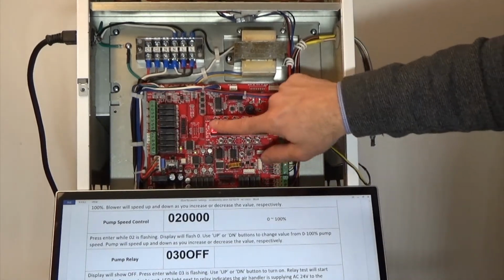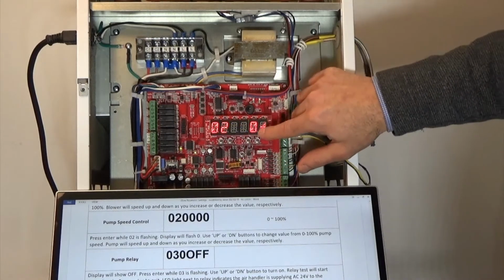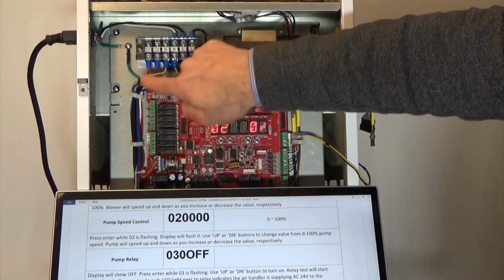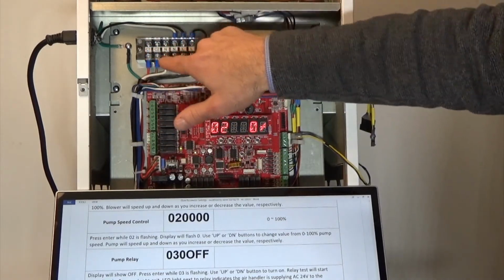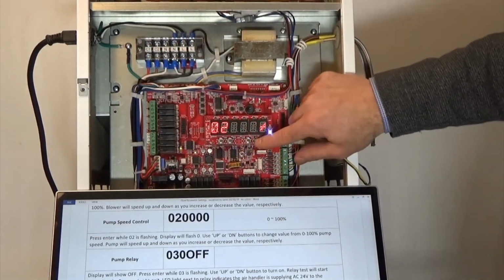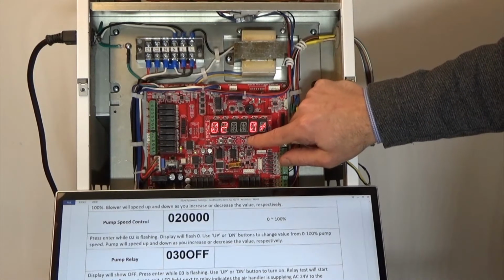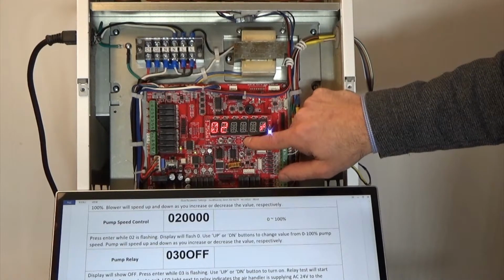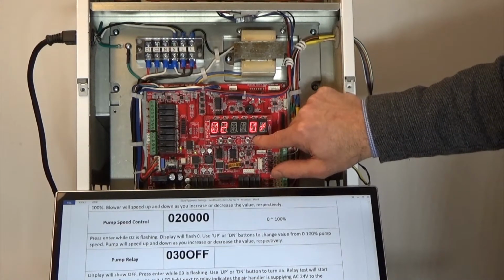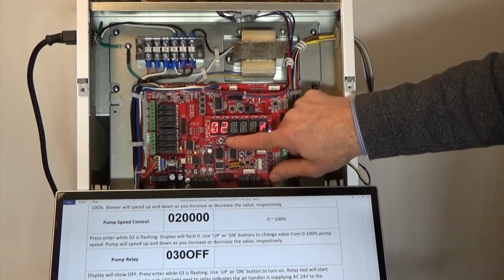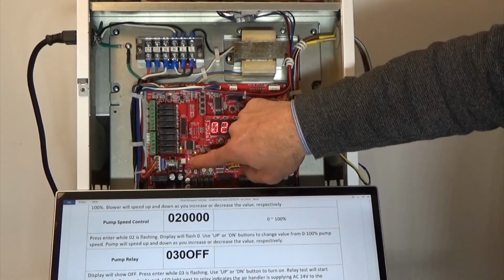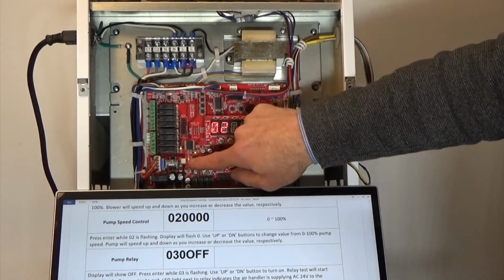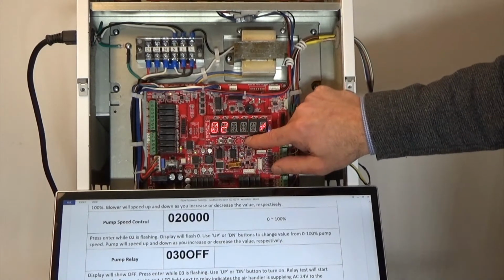So actually, this is one thing, when we're using the variable speed pump control, which goes out of these two wires, it's the red wire that follows up. It wires to the C1 connection. That's providing a variable power output, and you can see on the board when we're actually using it, that the red light will illuminate as soon as we start to go into the range for that pump, and it will get stronger as we hit 100%.